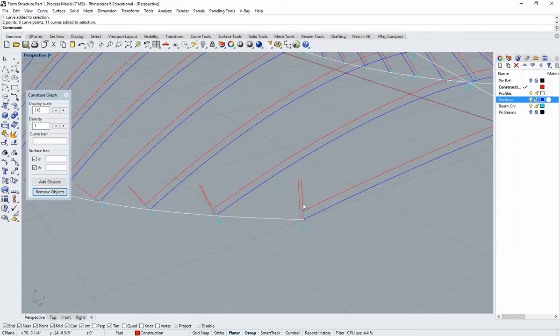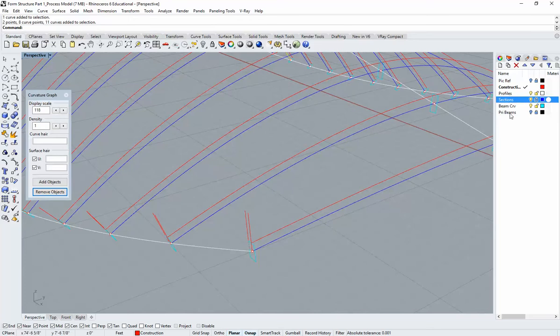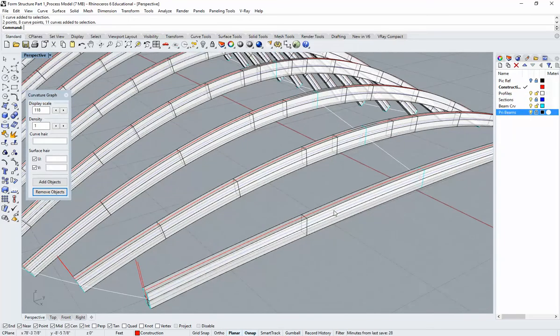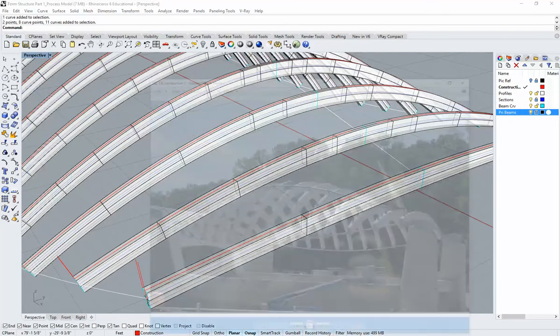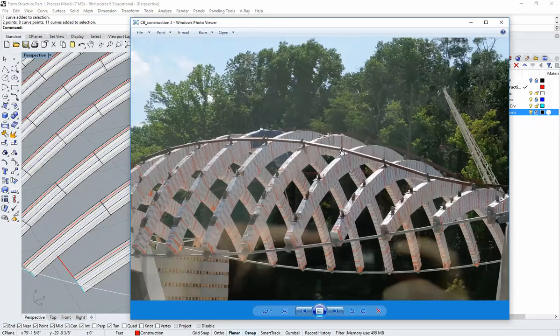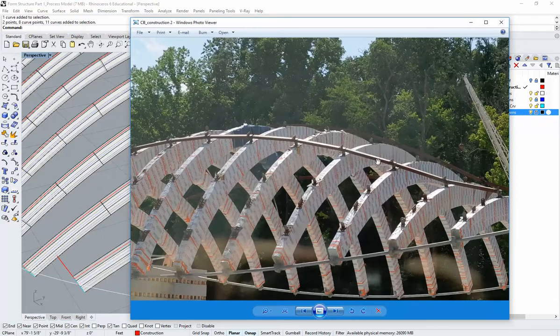want to find another offset from this point, because this line is the top of our primary beam. And since we're not modeling every single detail of the building, what we're going to want to do is float these secondary structural members up and over the top of the beam. So I want to give a little space here, even though we're not going to bother modeling these brackets for now. But I still want to model it with a little bit of space there, so that I don't have any intersections, and so that if I did want to go back and add this detail later, I could.